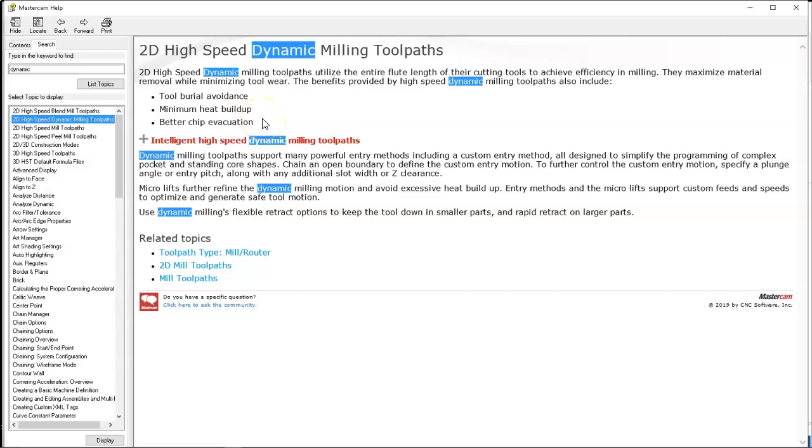All right, heat buildup, the whole purpose is to have the chip carry the heat away from the tool and away from the part. If you're done with the part and you pick it up and the part's warm, the heat's going the wrong way. It should be in the tool or going away with the coolant. I think I mentioned one of the machines I run has the coolant tank in the casting, and every time I filled it up, it made it barely a month, and it smells like you don't want to know.